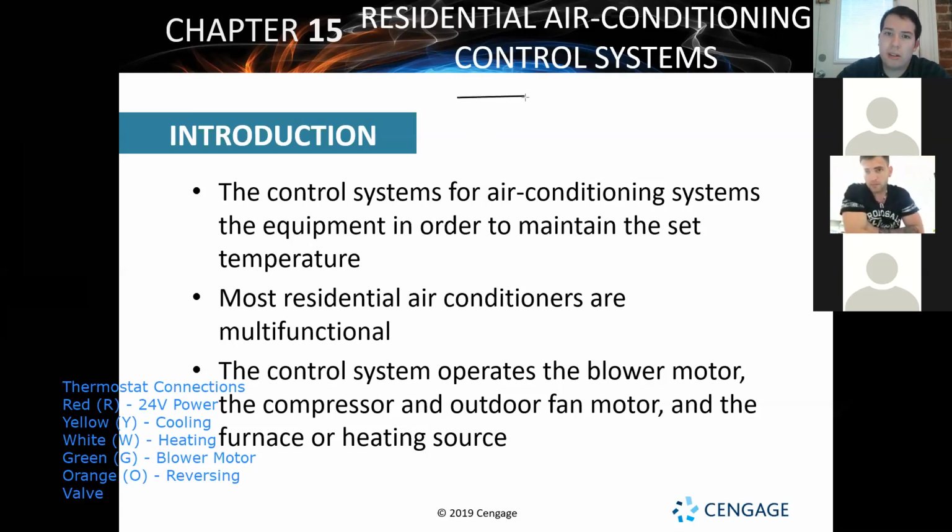A thermostat, keep in mind, is just a temperature switch, right? There's two ways that temperature switch can be set up. They're going to close on a rise or close on a fall. All right. So you would have it where the thermostat's got its R connection.